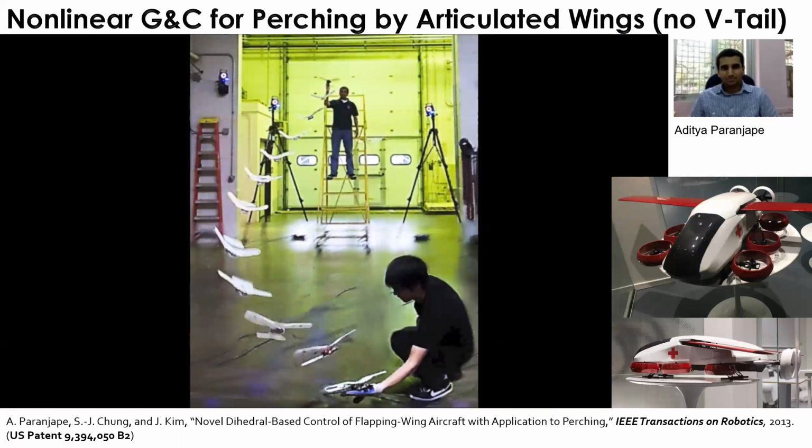So we learn the model using a deep neural network. The problem with this kind of method is that you don't really know how large the output is, especially if you go beyond the original training bound. For example, if you landed at a certain velocity or certain state, distance and height, but then go beyond that training region, you don't know what the output is going to be. So we use a particular technique called spectral normalization, so that you can bound the Lipschitz constant of this black box deep neural network.